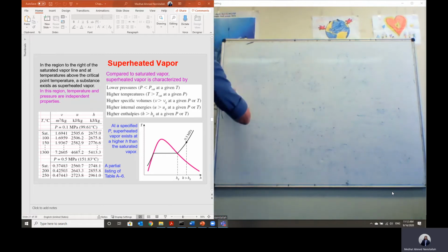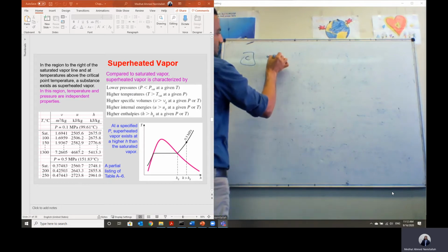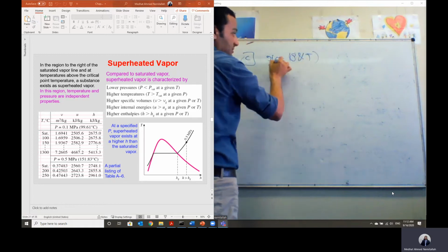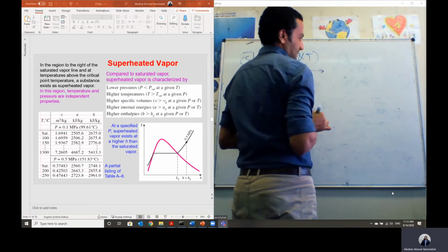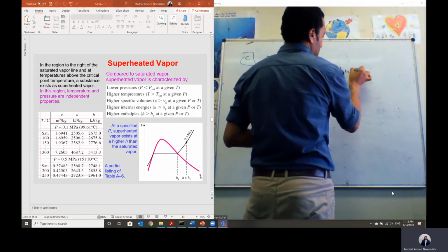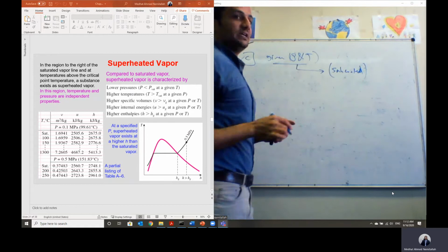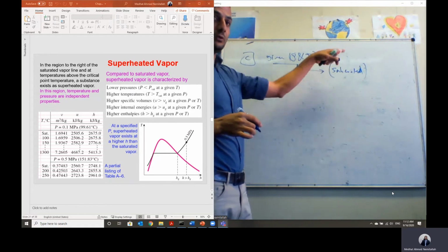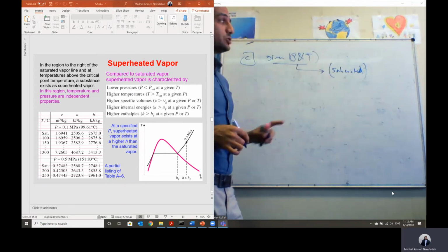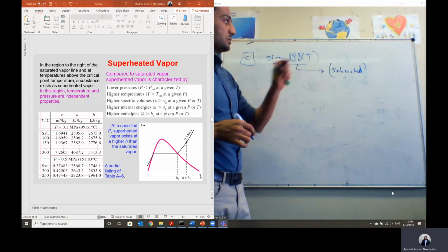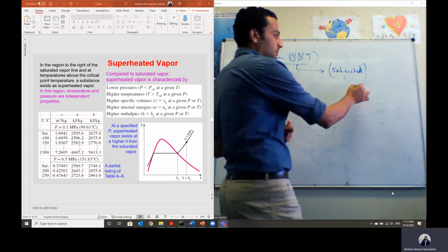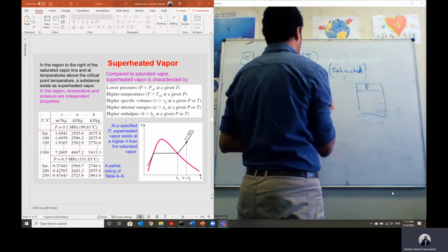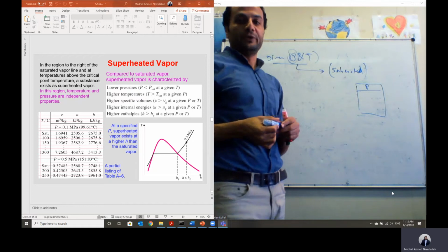So if pressure and temperature are given, case C, and I have made all of these checks, and I found that the state is subcooled. So I am confirmed that the state is subcooled. I got T saturation and compared with the given temperature. I found the temperature is less than T saturation, so the state is subcooled. But when I went to the subcooled table, searching for the required pressure table, I didn't find this value of pressure.